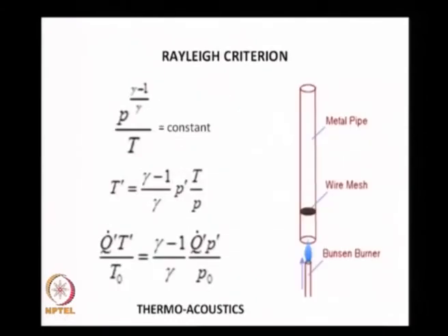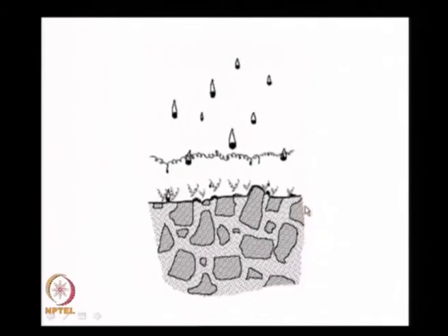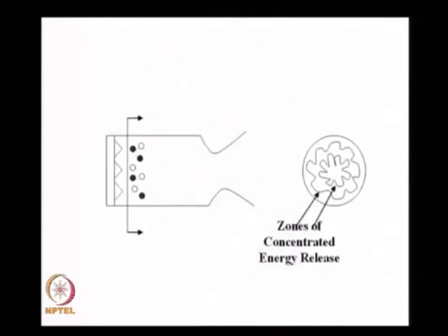This is what we just now saw, thermoacoustics. Maybe we put a heat source here and we could hear the sound, that means pressure perturbations growing. And if I have a solid propellant, these are all AP particles in the resin over here, I have a flame standoff here, aluminum particles are burning here, it dampens the wave just like the boundary dampens the wave, and therefore you have phi minus sigma which leads to this.